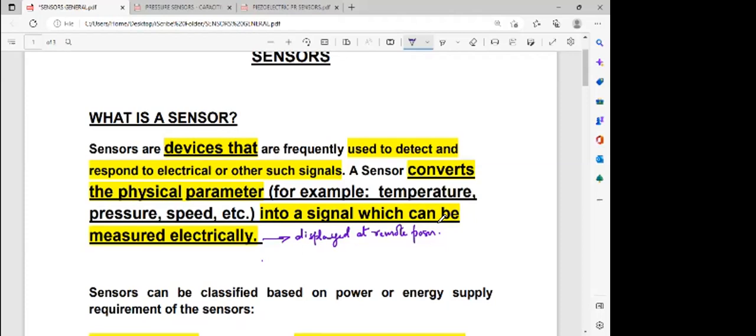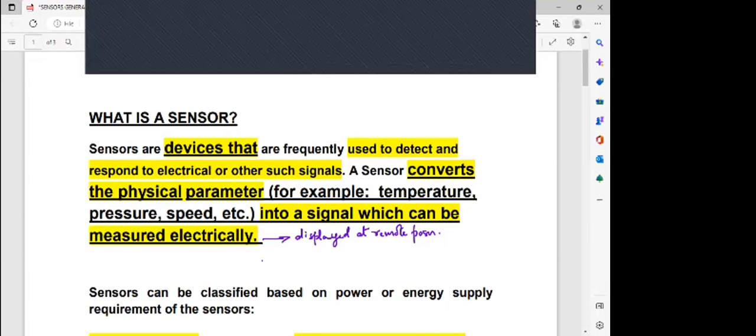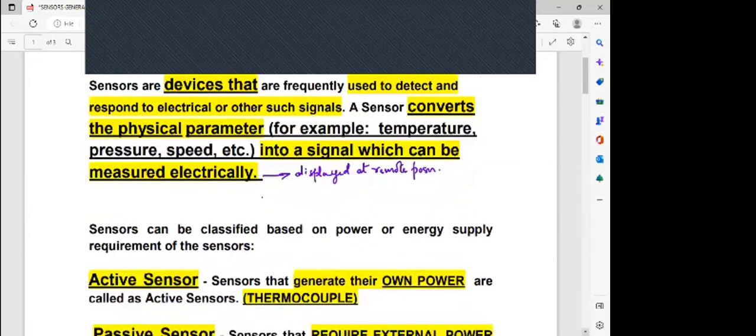When we did the AMS system, we have 2 screens, isn't it? So we can read it on those screens. We open that particular page and we can see the particular parameter that we are talking about. In this case, the exhaust gas temperature of that particular main engine unit.